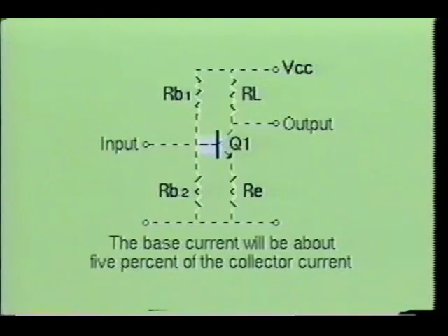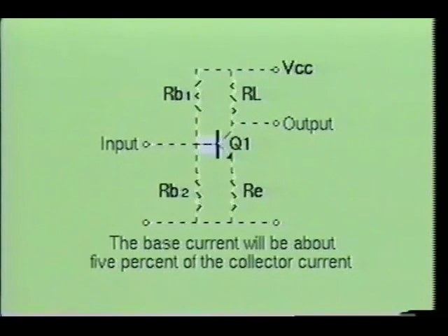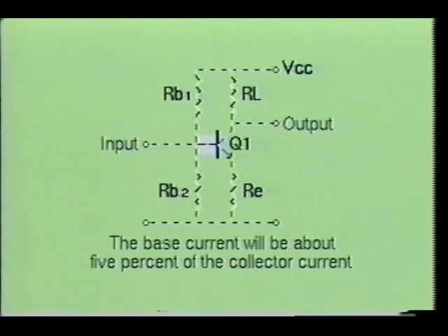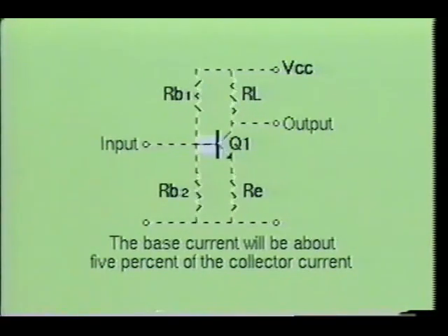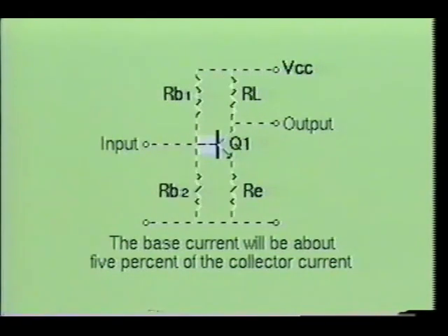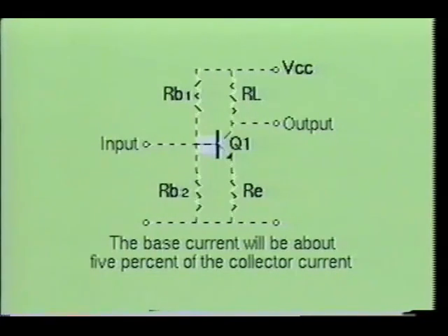Since most small signal amplifiers have a current gain of 20 or more, the base current will be 1/20th or less than the collector current flowing through the transistor. Therefore, this small base current will have little effect on the base voltage. The stability produced by the voltage divider bias circuit makes it a very popular design for amplifier biasing.